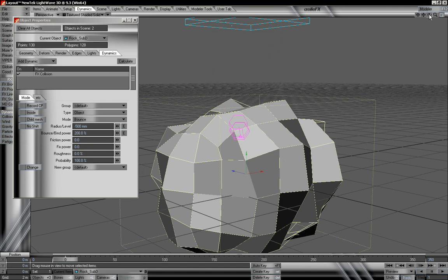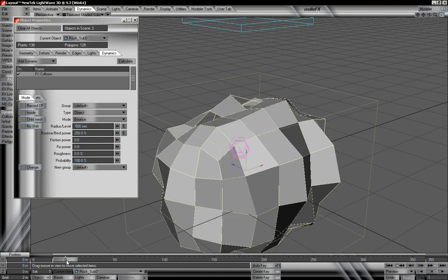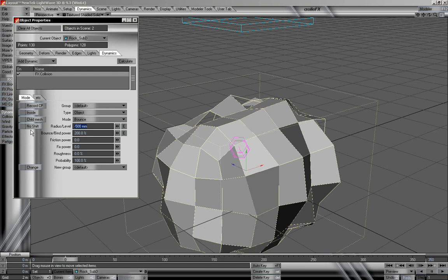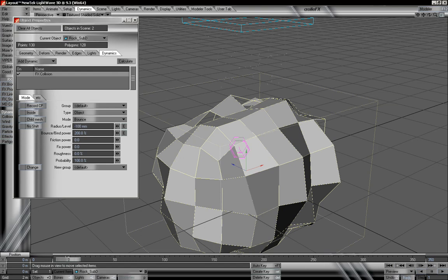sometimes need for certain scenes, or if you don't want it directly bouncing off the outside of the object, maybe you need it to go inside for a certain hypervoxels effect in order for it to look correct. Because of the way that hypervoxels are generated in their centers, you might need to go into the object a little. So we could even set that to a smaller amount where it's just negative 100 millimeters, and it's just slightly going into the object.